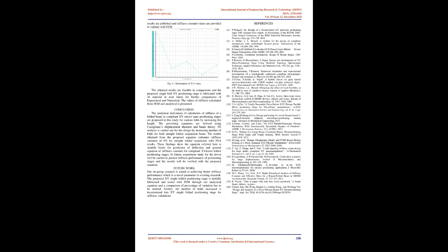Results and discussions. The parameterization is done for the XY folded suspension beam stage designed to know the thickness of the center stage and the thickness of the beam. The self-weight analysis is done to find better results for the stage design. The optimum range for the self-weight analysis is 1 to 2 mm thickness, and the parameterized optimum value of the beam is 1 to 1.2 mm thickness. The candidate point results are taken in ANSYS and shown in graphical format from the above findings.